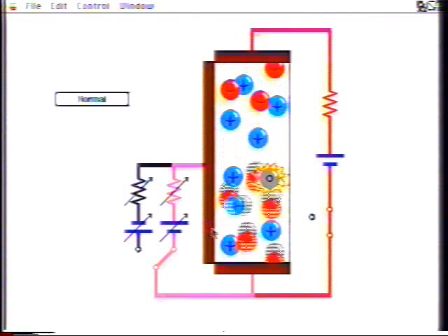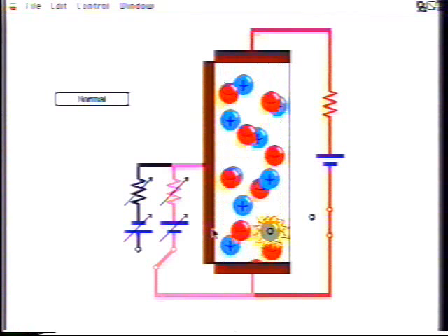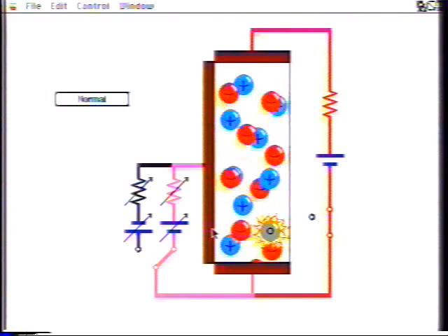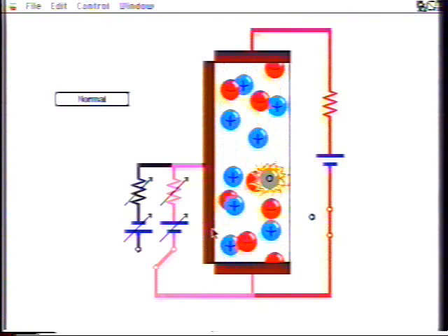The result is that there is a steady-state DC base current required to maintain a given total charge of holes in the base region in the presence of recombination.